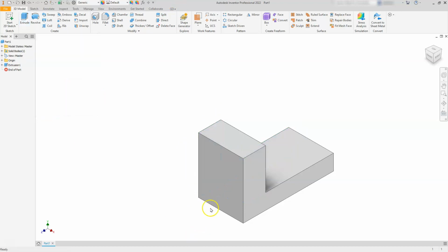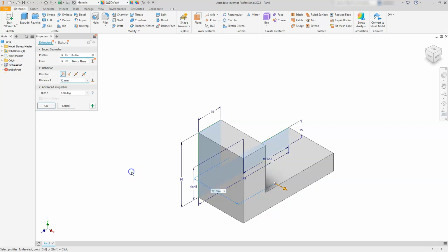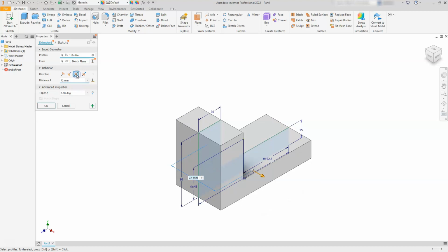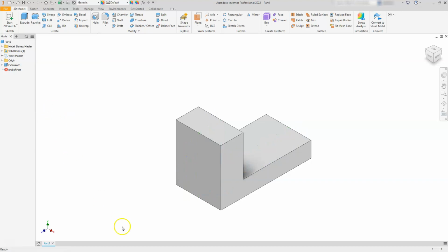So if I went ahead and did it here, remember that that is going to be controlled here. If I double click on the little icon where it says extrude right next to the extrusion 1, that'll take me back to the command, and then that is going to allow me to shift it to where I want or make any other changes in here that I want. Let's go to OK. Let's go ahead and create this front part on this face.